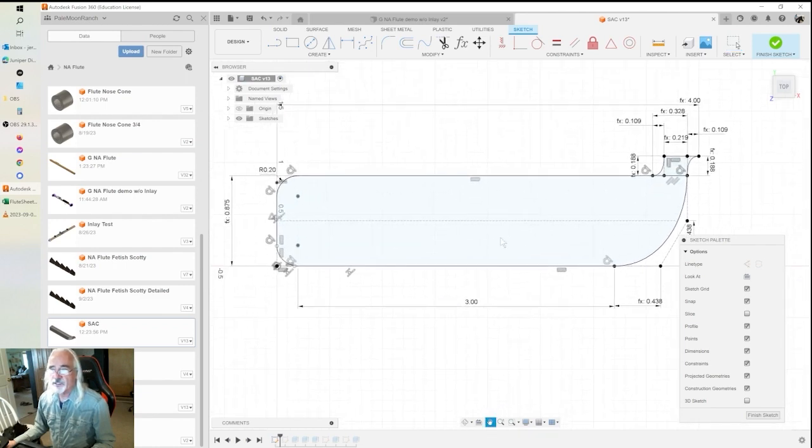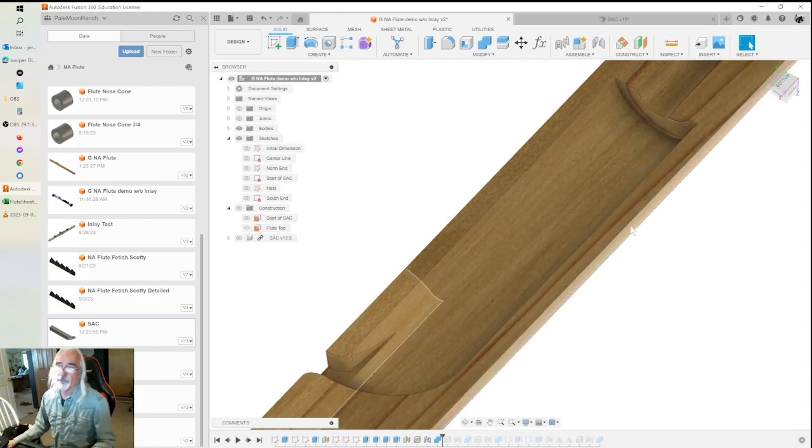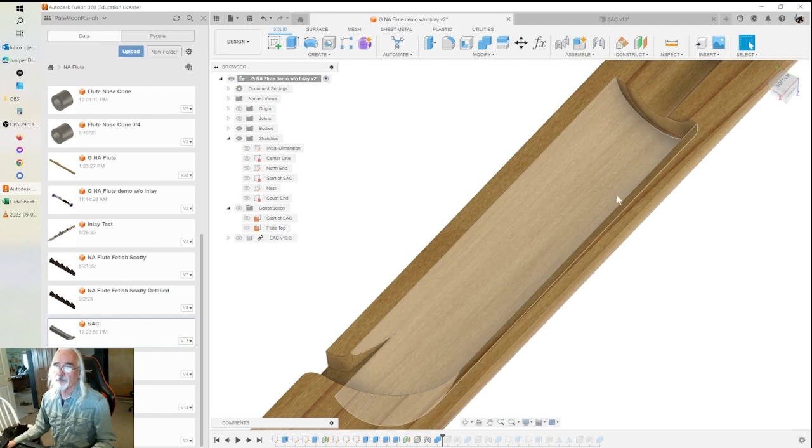This is really just aesthetics. It's really how I wanted it to be. You want air to travel smoothly through this. So this started as a rectangle, and I used the fillet tool to put on these edges, and then I used a control point spline here to create this nice curve that I'll show you over here. That's this curve right here, so that the air flows nice and smooth through here. Okay.